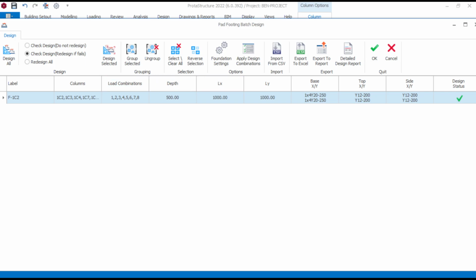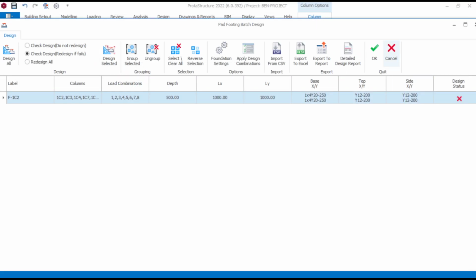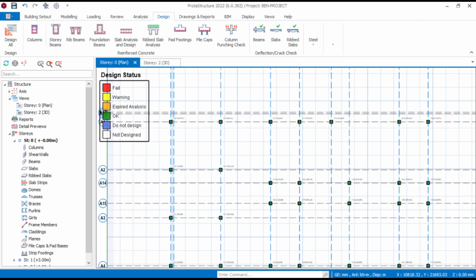Then after that, you just click anywhere outside. Let's wait for it to come up. It's going to take all the part footings and pick the worst case scenario for everything. Okay, it's actually giving me a depth of 600. I believe that is too much for a one story building. So let's cancel this. We're not going to go with this method.